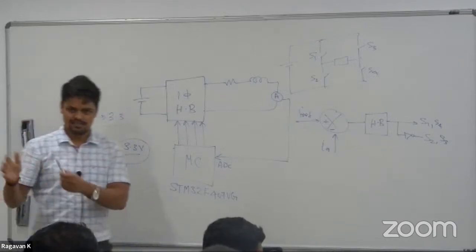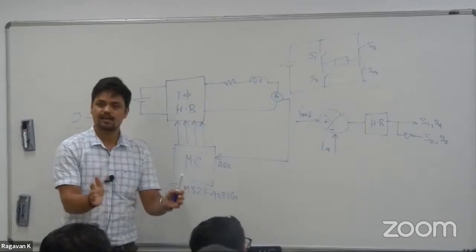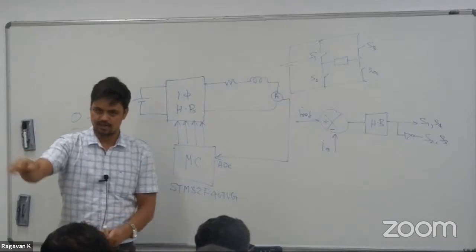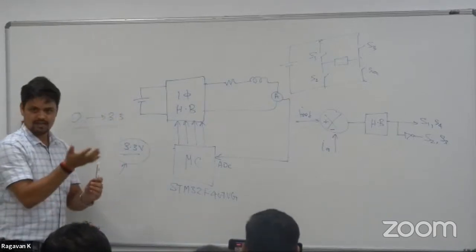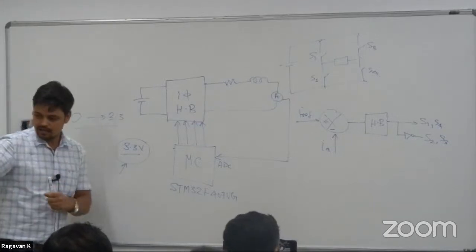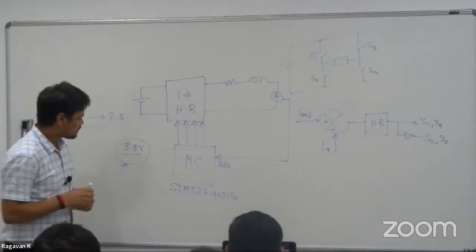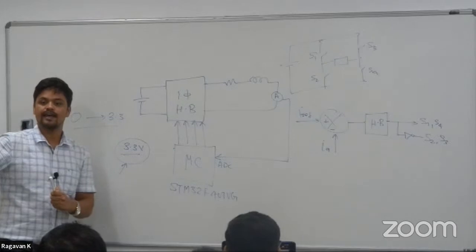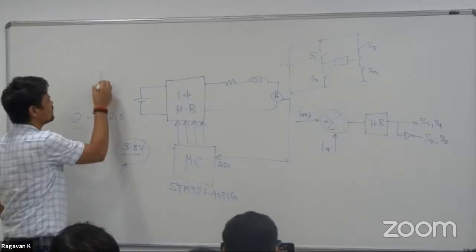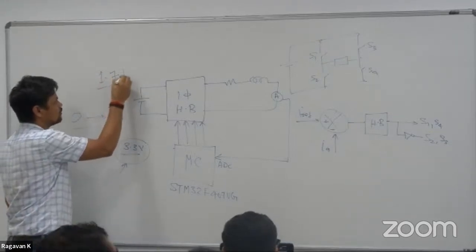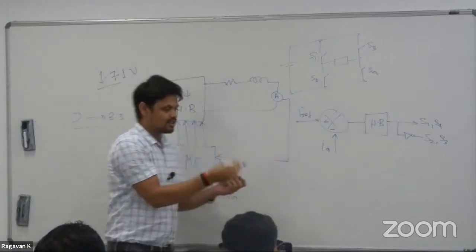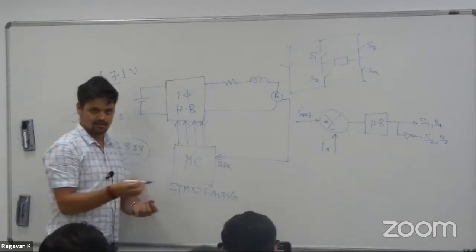For that we need a sensor first of all, and then signal conditioning also, right? I will show you this current sensor and then the signal conditioning. For the offset there is no option to adjust it, but for controlling the gain, for how much current you want per volt, it is there. And for offset we have made it fixed at 1.71 volt. Whatever is provided at the time of sensing, in the code we track that.